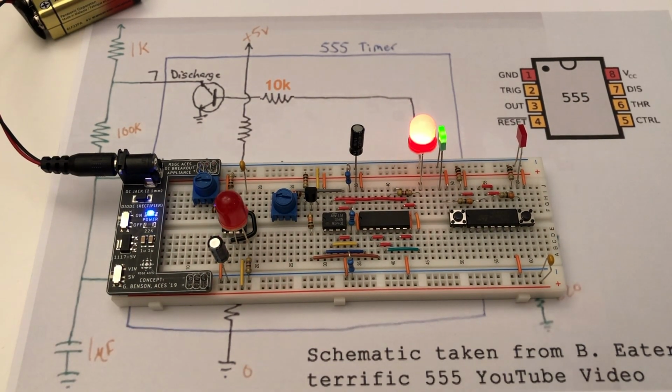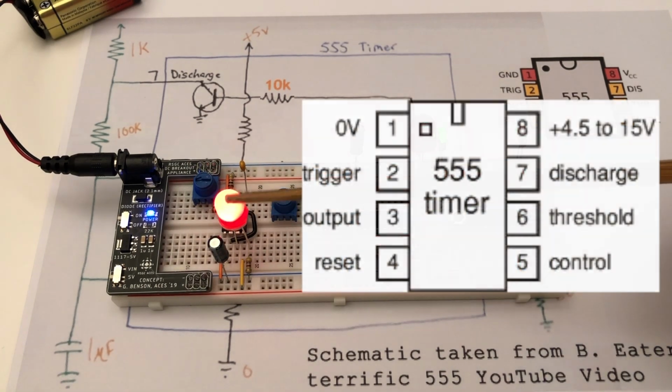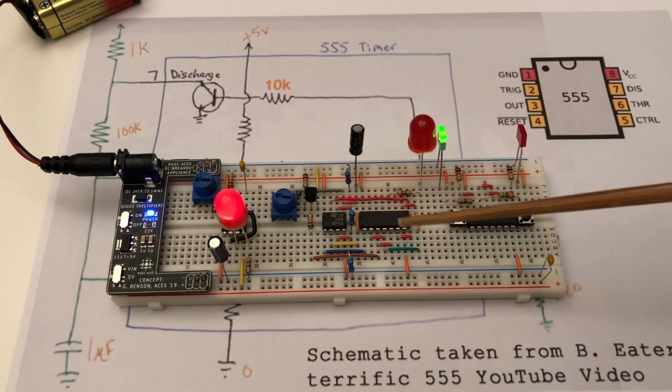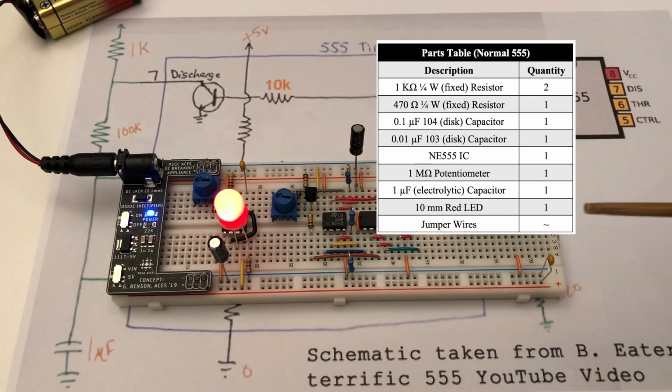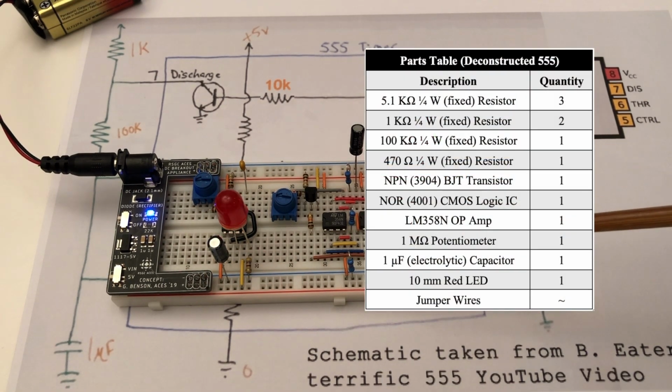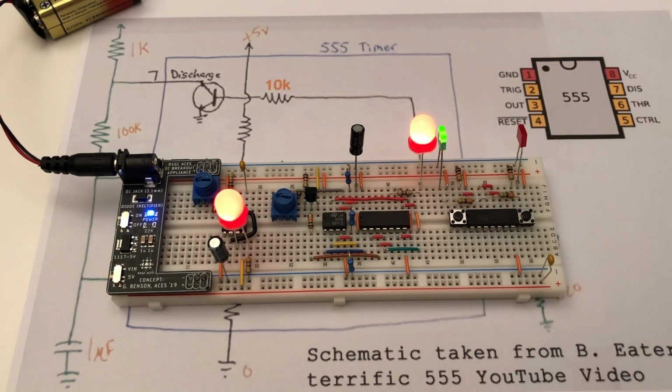The purpose of this circuit is to produce a square wave from the output pin of the NE555, and then to dive deeper and understand the inner workings of the chip which create the oscillation. These are the parts I used for the normal 555 and for the deconstructed 555, which I'll be going over in this video. The 555 can be built in three different modes: monostable, bistable, and astable, which is this circuit.